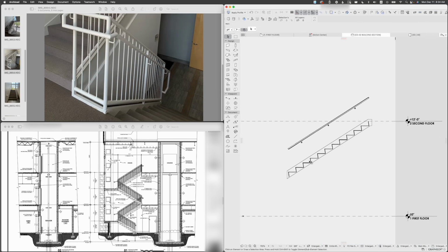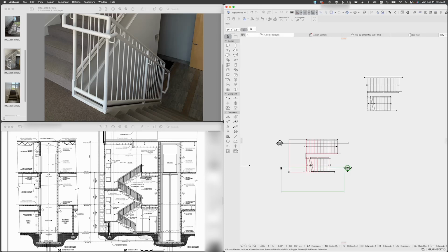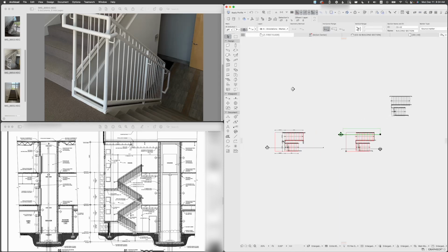Now I think it's actually better to build finally some landing here and there. So let's do that so we can better see and understand our stairs. And I already built a landing here. So this is just a slab that has concrete material, and it has 4 inches. I can show you how I did it. So I just select a slab and make sure the material is set to be concrete, and then 4 inches for thickness, and I set up the height 5 feet.